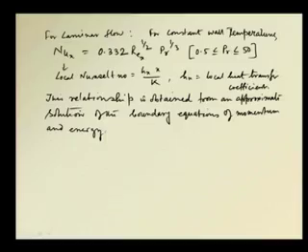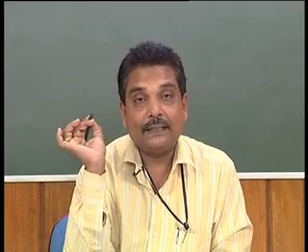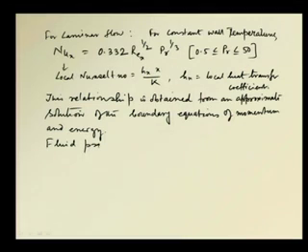Now, the fluid properties are measured. This is very important. While we will be using any correlations, one thing we have to understand is the temperature at which the fluid properties have to be evaluated, because some of the fluid properties can be drastically changed due to the changes in the temperatures. So, we should be very careful about that particular issue. So, here the fluid properties are evaluated at TF. TF means film temperature.